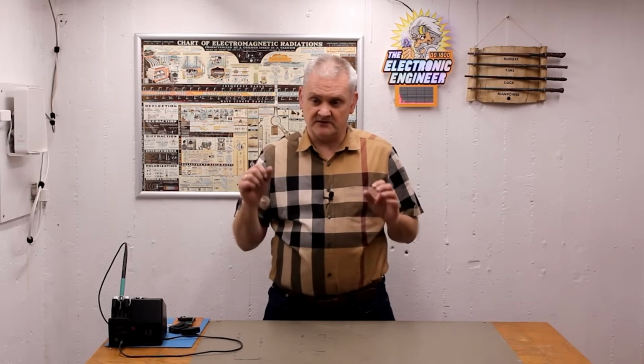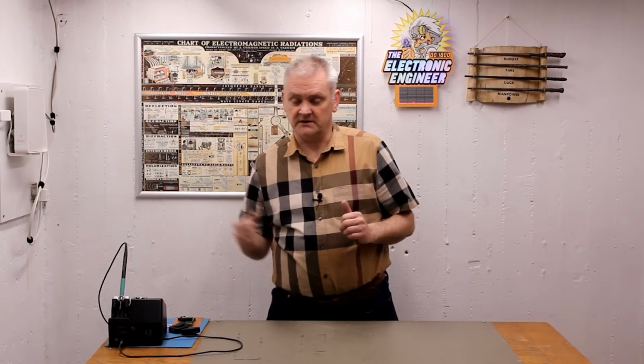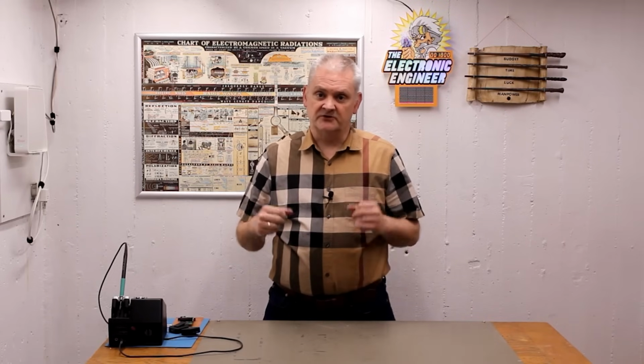Okay, imagine a piece of sound and you freeze it in time. Then you take a sample of that moment and you analyze it. You look at the frequencies that are present and how strongly they are present. So basically what we do is we take the peak value of each frequency and we save that data. We do that for the next sample and the next and so on. What we get is a whole table with peak data of frequencies. Now the question is, could we use that table to recreate the original audio sound that the table came from? And that's exactly what we do with vocoding.